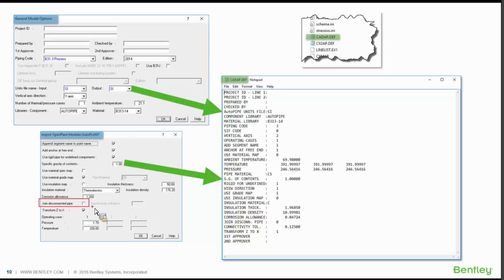So this will actually use the connectivity tolerance set over here. And within that tolerance, it will join the disconnected pipes. And you won't see those random anchors being placed throughout your model due to this option up here, which would add anchors at any free end within your model. So using these import options will really be helpful, going through, looking at the wiki page and understanding what each option means. Right, thank you.